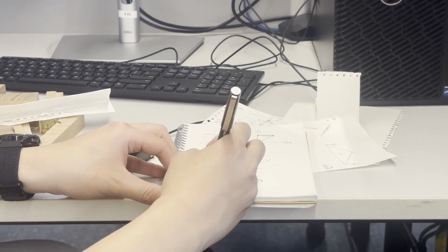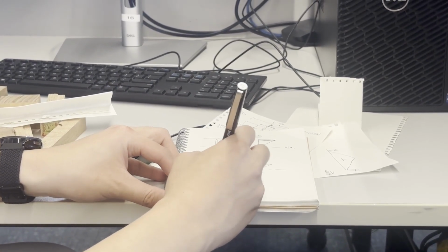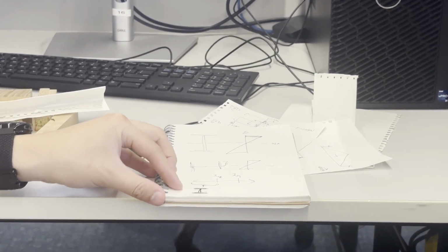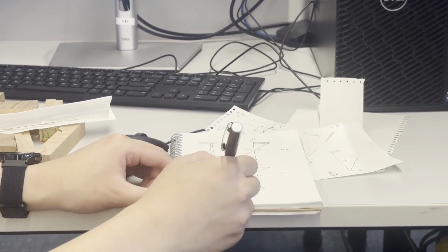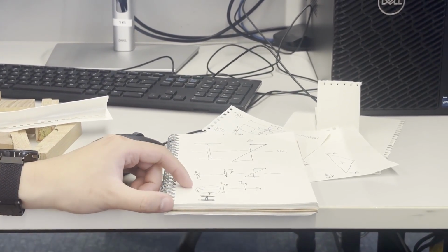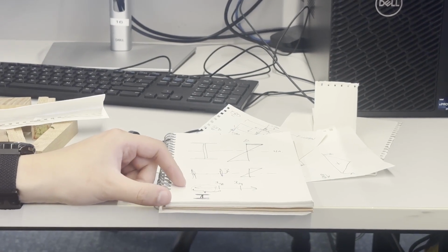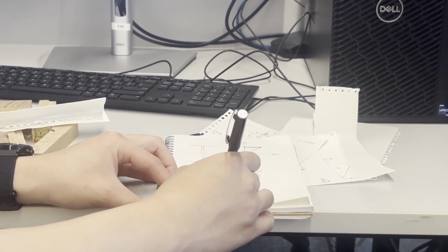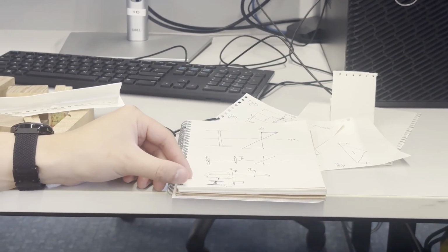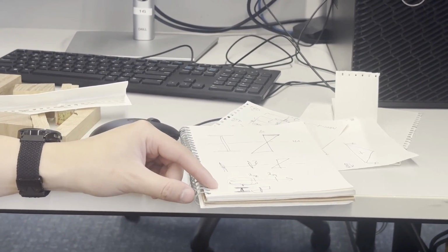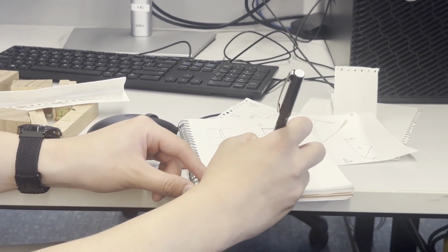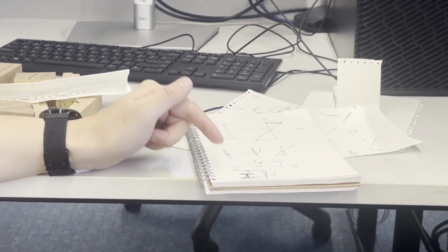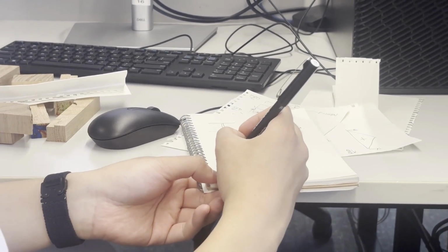For a compact section, one that's very thick, where all the plates are very thick, all these elements are going to reach plasticizing. So on a stress distribution, the whole thing can plasticize. It can keep bending and bending until the entire thing is plasticized. It can theoretically reach that point. So that's called a compact section.